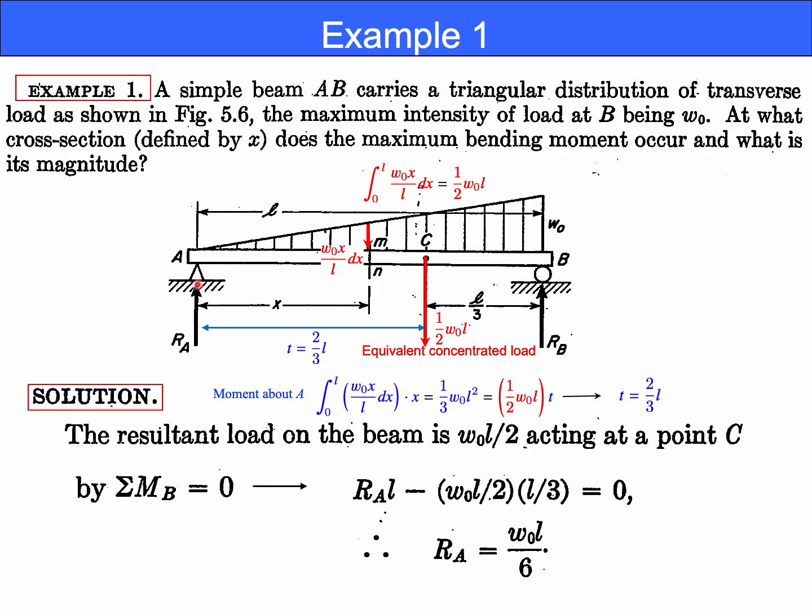At the points A and B, only the reaction forces exist because the beam is simply supported and no reaction moments exist. The reaction forces are assumed to be Ra and Rb at A and B respectively. We can determine them by considering the balance of forces and balance of moments.